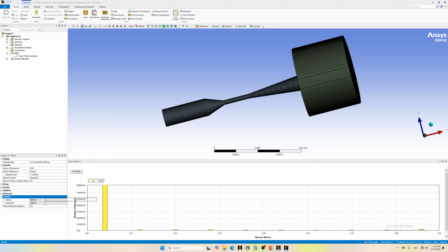It's okay, you'll get quite a good result, but to be sure that your result is accurate, normally you have to do what is called mesh independence. So what does it mean? You will increase the mesh, the number of cells in the mesh. So let's say 100,000, 500,000, 1 million, 2 million, and the solution shouldn't change as you increase the number of cells.